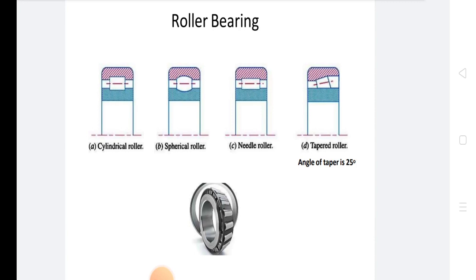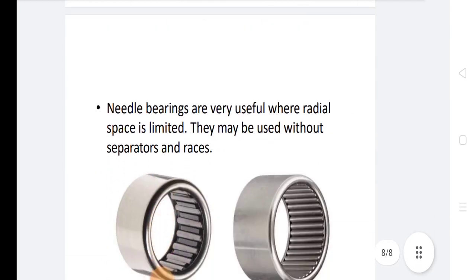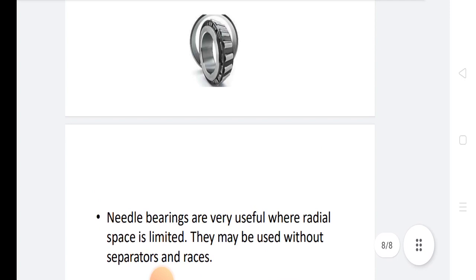The recommended bearing life for vehicle application is given like this: automobile cars, 50 million revolutions; trucks, 100 million revolutions; trolley cars, 500 million revolutions; railroad cars, 1000 million revolutions. So it is a very important point.